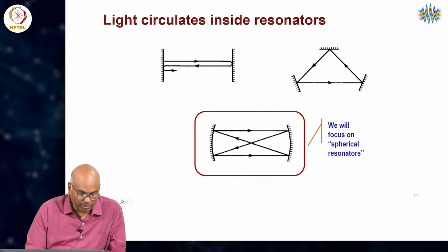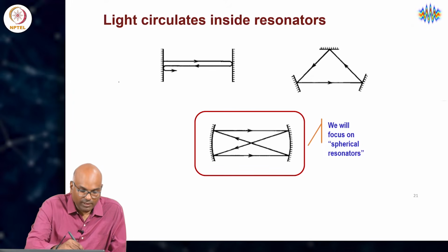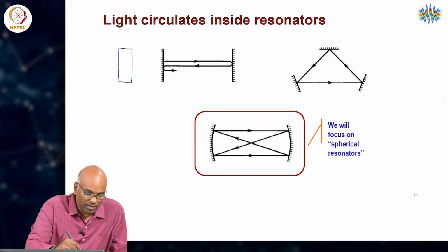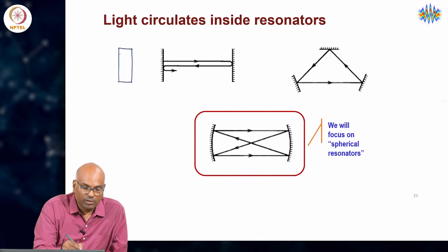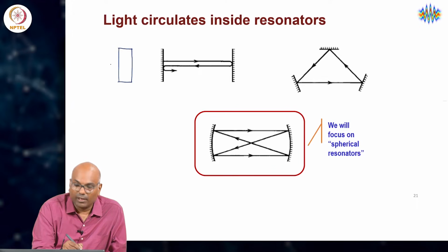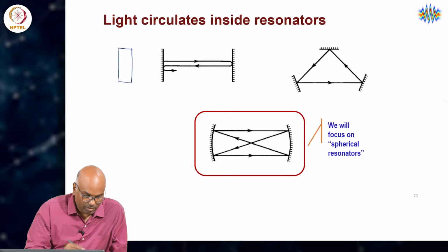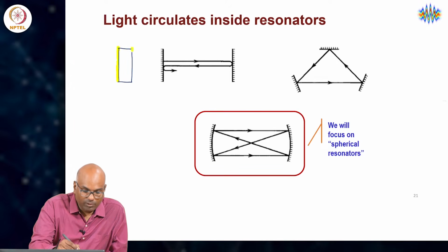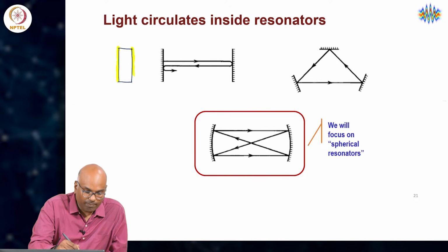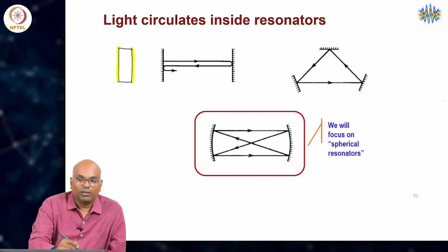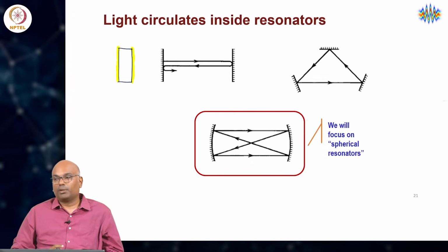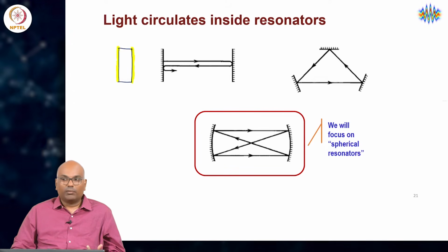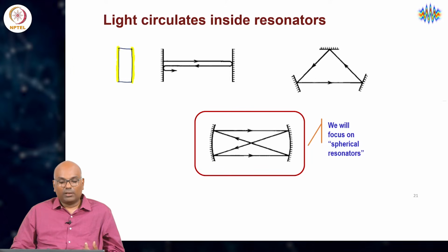An etalon was essentially a very nicely engineered piece of glass with polished flat parallel surfaces on either end, which were also very highly reflective. They are very likely coated with some dielectric multilayers in practice, and they actually operate with high finesse in a reasonably narrow range of wavelengths.